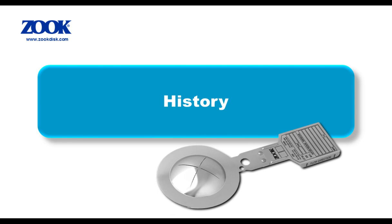Rupture disks have been around for a very, very long time and have earned a solid reputation for successfully protecting all types of pressurized equipment. The original rupture disk was simply a piece of thin foil clamped between a couple of pipe flanges. Designed to be the weak point in the system, as the internal pressure increased, the foil yields because it is thinner and therefore weaker than the vessel wall, eventually failing to safely relieve the overpressure and protect the integrity of the system. It was simple but very effective. The first patented design was in the early 1930s and is still produced by all manufacturers today.